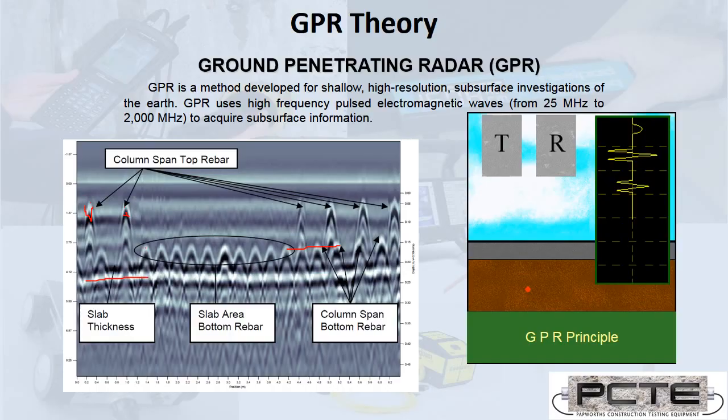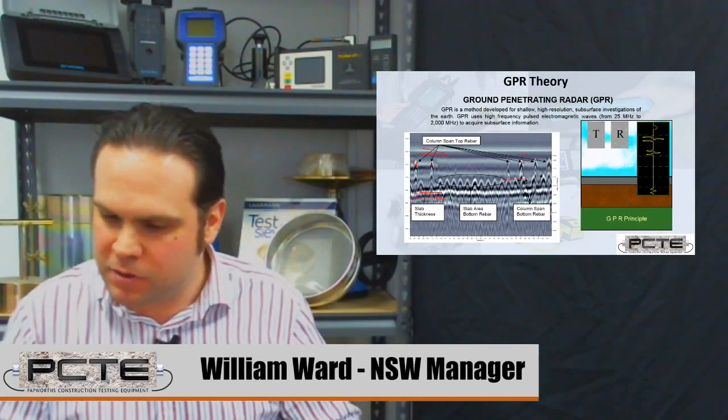So with that GPR scan where we saw the depths measured here, we would make that measurement very precise, and then we're going to take into account that reinforcing bars usually sit one on top of the other. So we'll look at the measurement here to here, so top surface to the top reinforcing. Then we're going to scan at 90 degrees along the surface of the concrete, and we're going to look at reinforcing in the other direction, and we're going to look at measuring the depth of that second bar, which should be in contact with the first. So the difference for the steel on top should be an estimate of the reinforcing diameter. As you can see, it's not really an ideal measurement, but it is something that can be used.